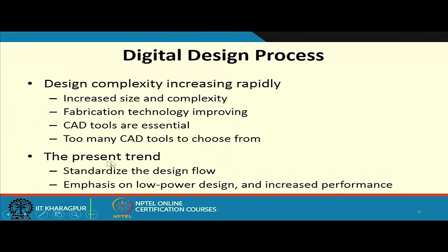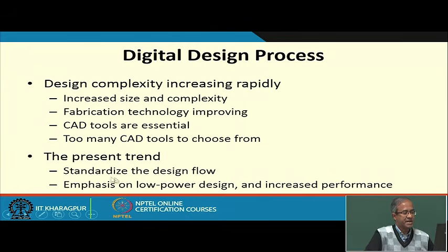So, the present trend, as I had mentioned, is to standardize the design flow. Design flow means what are the tools I would be using. Like I had said, in our case we would be using Synopsys in the first few steps and Cadence in the later steps. And of course, with the increasing emphasis on battery operated devices and various mobile computing platforms, greater and greater emphasis has been laid on low power design without sacrificing performance.